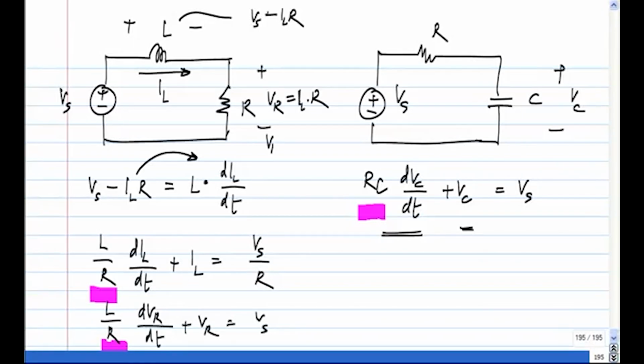Now the inductor is sort of the counterpart of the capacitor with voltages and currents interchanged, right? So you cannot have a discontinuity in inductor currents if you have finite voltages, but clearly if you apply a current source directly to an inductor, you will have discontinuities, right? So similarly, you have to look for nodes where you have only inductors and current sources. In that case, if you have a step in the current source, there has to be a step in the inductor currents also, right? There is no other way KCL will be satisfied.